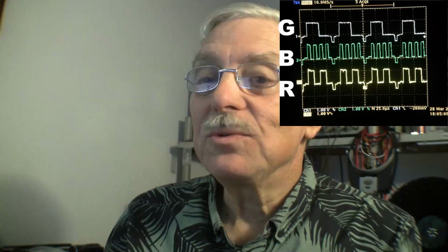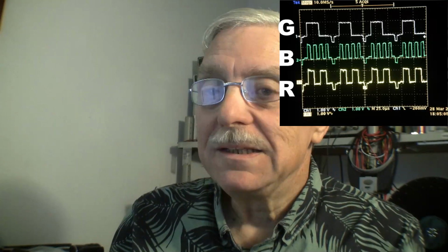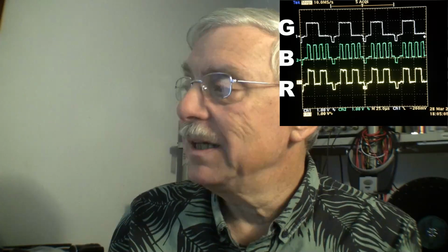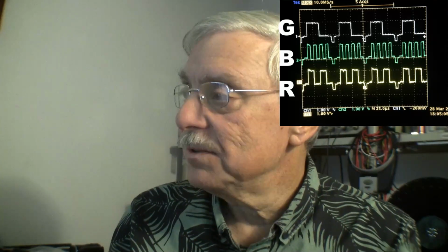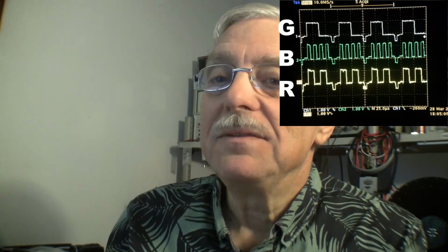So that is the process of red, green, and blue being converted to Y, R minus Y, and B minus Y color difference signals. And in the 10-4 Eleanor deep dive, you will see the Y equation played out in resistor values. Very simply, don't panic. Nothing to panic about. And in fact, you will laugh when you see how easy it was to get those resistor values.